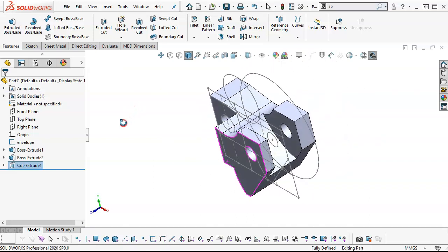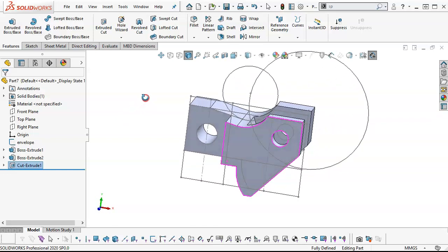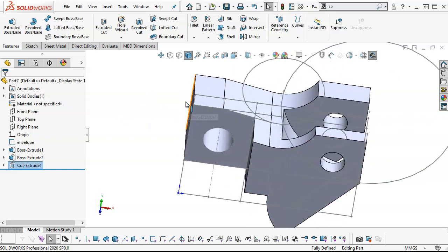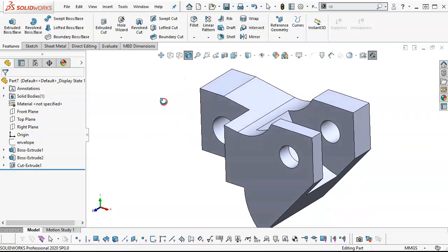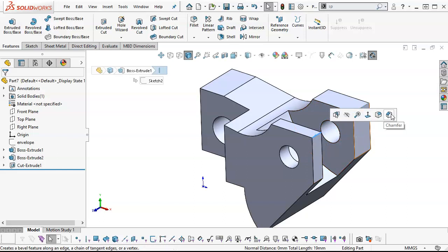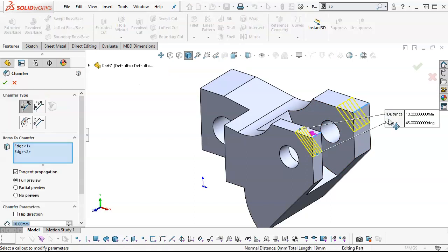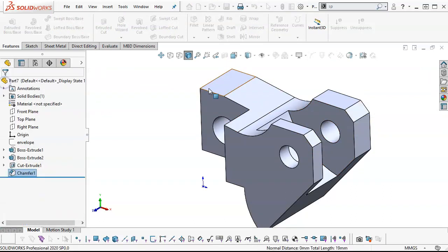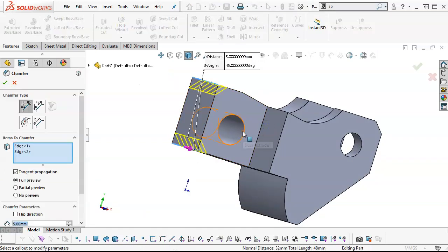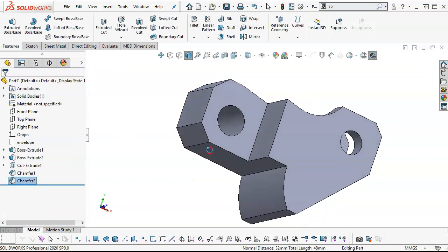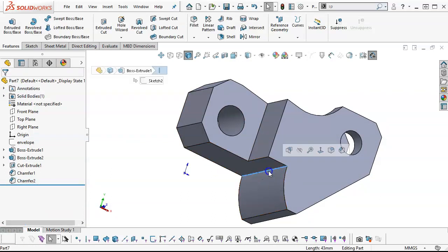And I don't think we're given any numbers there. So that all looks pretty good, like we got it. So I'm going to hide the envelope. Do a quick double check before we start in on the chamfers. So 5 millimeters by 45 degrees. Come over to the chamfer and set it to 5. The back is set to 7. And there is a radius of 5 in the lower.